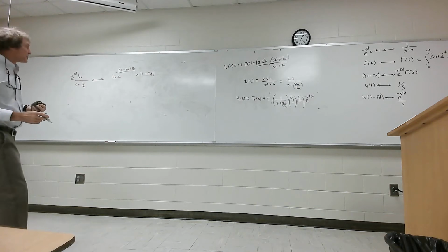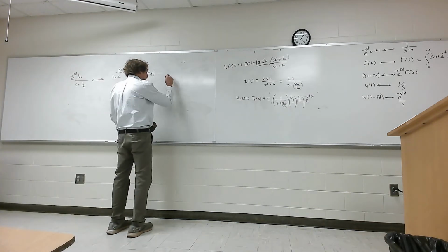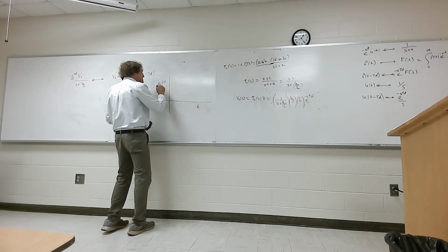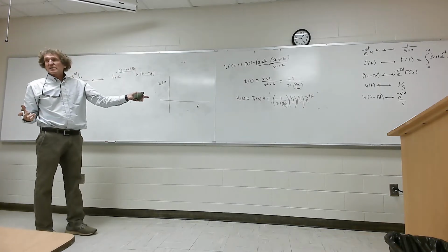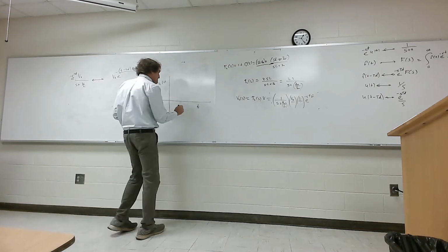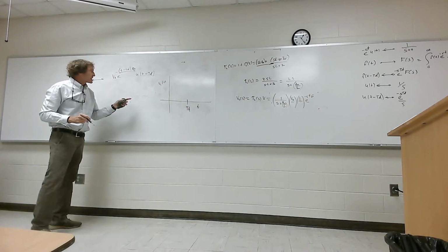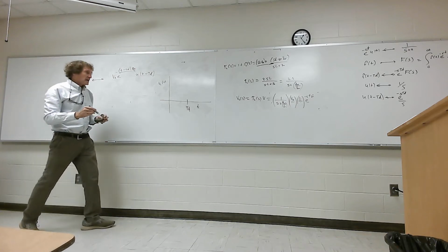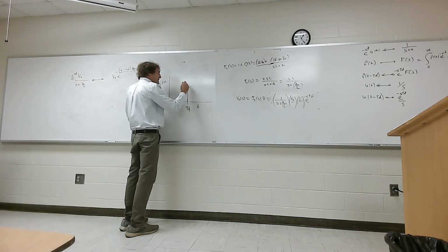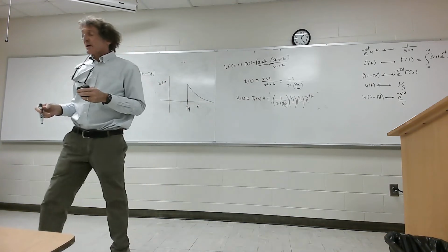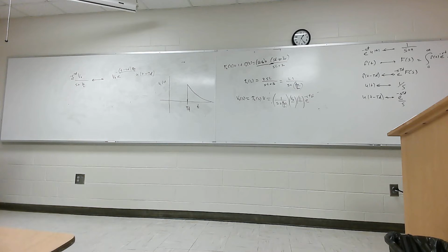What does that look like? This is time, this is voltage at the load, as a function of time. Nothing happens until what? TD. So that becomes important. Then at TD, what does it do? Instantly, it's got a value of V naught, doesn't it? So it spikes upward, and then it asymptotically goes to 0. You all see that? The inductor looks like a short at DC or at very long times. Once the transient settles, it's a short circuit. You all follow me? Okay.